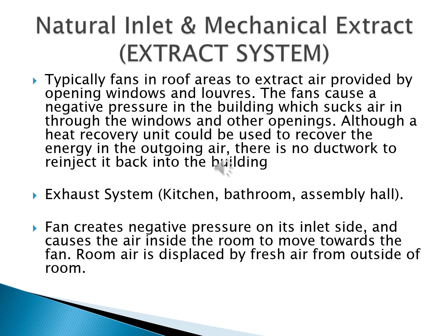This is the most common type of system, which is also called an exhaust system, and it is used for kitchen, bathroom, and assembly hall. The fan creates negative pressure on its inlet side and causes the air inside the room to move towards the fan. Room air is displaced by fresh air from outside of the room.